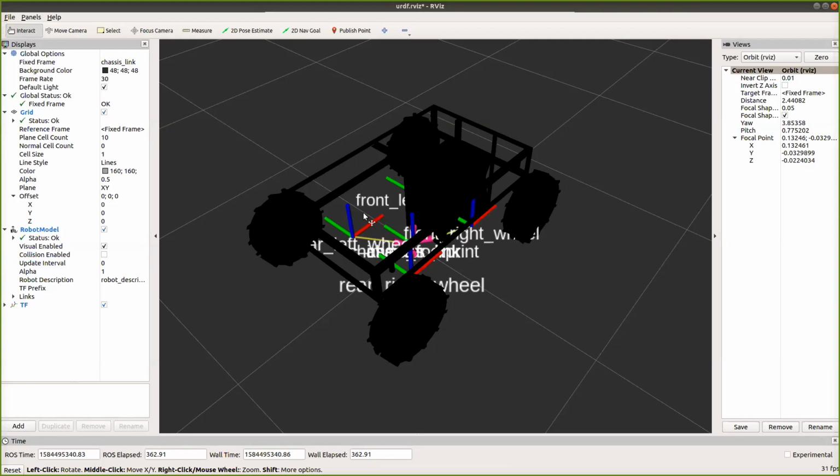Yeah, I learned the hard way. Originally I built all my processing on my laptop and had very minimal on the rover, and I have 4-wheel drive, so each wheel has its own motor. So I have 4 motors and 4 wheels, right? And I would get 3 wheels to run, and the 4th one wouldn't run because it got hung up on a network issue, or one would run, all that sort of thing. So I struggled with that for a while. Now I know I've got to keep all of that type of command on the rover. All 4 wheels now always start at exactly the same time, because the computer right there on the rover is issuing those commands.